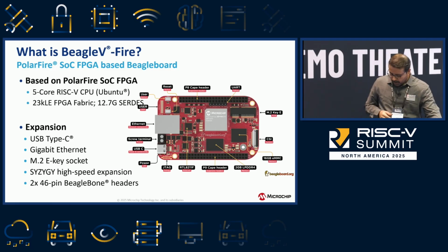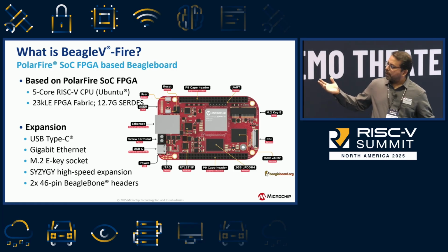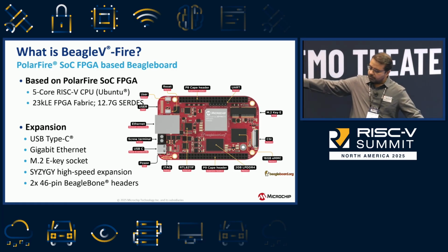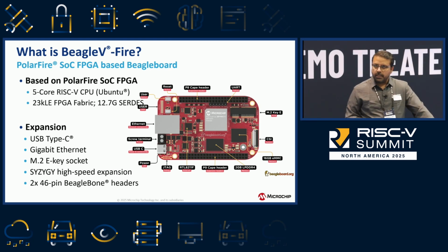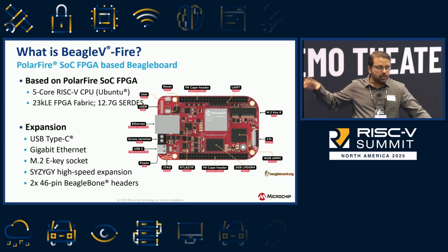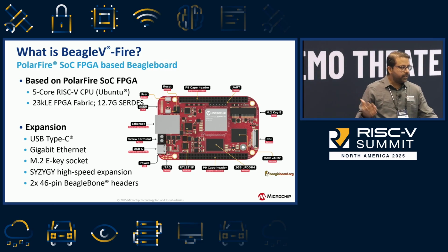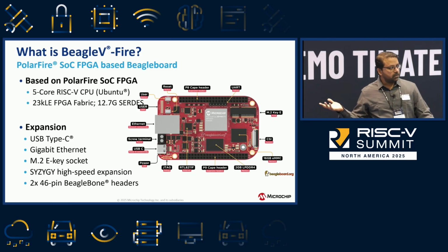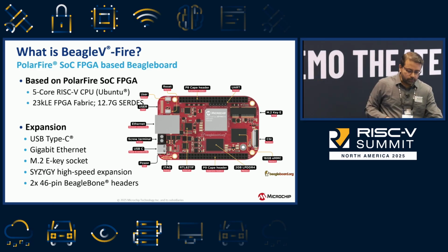What's great about BeagleBoard is that they build a whole ecosystem around boards like this. The 2 connectors that you see on the top and bottom are kind of their standard connectivity. Like you have shields in Arduino, hats in Raspberry Pi, the daughter cards that plug onto BeagleBoards are called capes. That's a standard form factor, standard connector, and you can build your own custom modules and plug them onto this board and create your own extensions. There are, of course, hundreds and thousands of people who develop these and publish them open source, and many of them you can even buy and use with BeagleBoard.